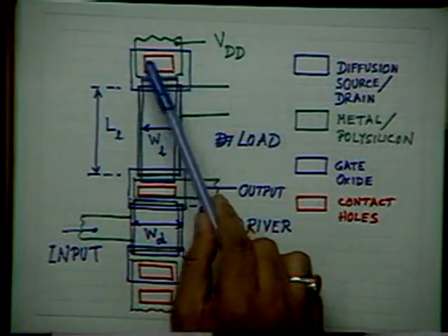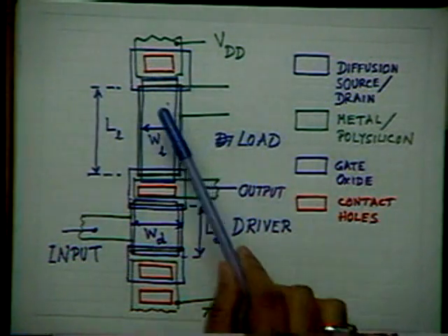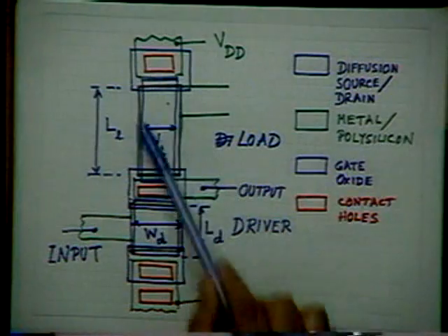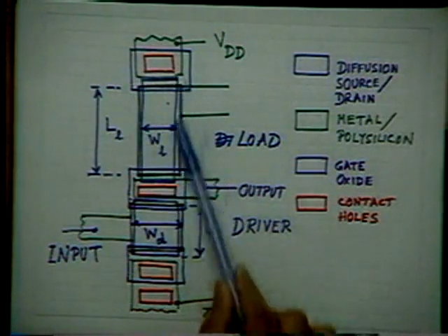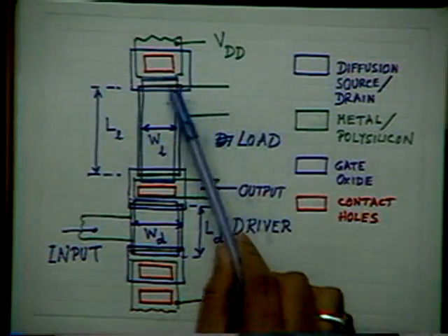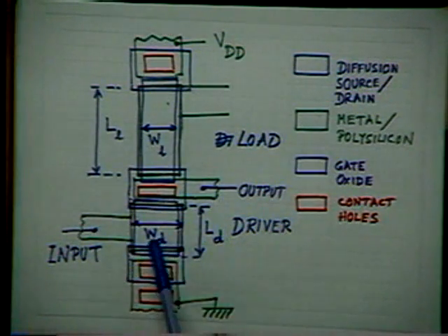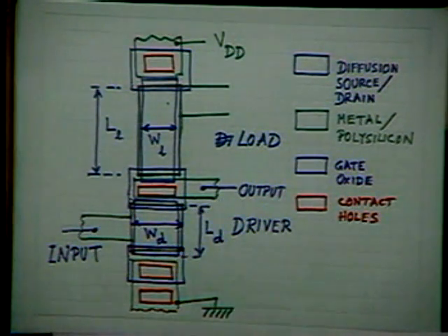And ultimately, we are metallizing the whole substrate by using a metal frame. Only before that, perhaps we have got a polysilicon here. Instead of metal, in this region we prefer to have polysilicon for various reasons, which I emphasized in the last class. But you see that all these window sizes finally determine the size of my MOSFET. And out of them, these four dimensions are very important.